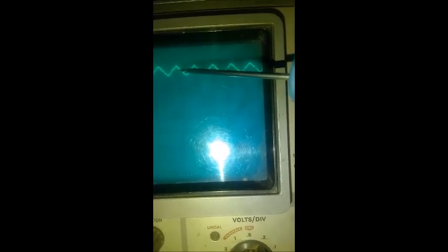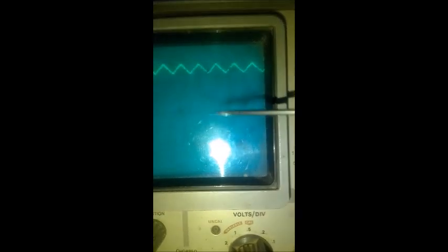So it's going that much up from the 6, and then that much down. It's oscillating here. It gets to a level where the input is now a high, and then it switches back to a low, with the time for the capacitor to charge. And this is the MOSFET capacitance.